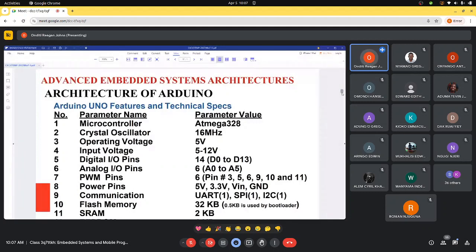This board operates at a voltage of 7 volts. It takes an input voltage. Remember, generally it operates on 5 volts, but in a scenario whereby you have a servo motor that works at maybe 9, 10 volts, then you can't depend on the 5 volts that the Arduino provides.